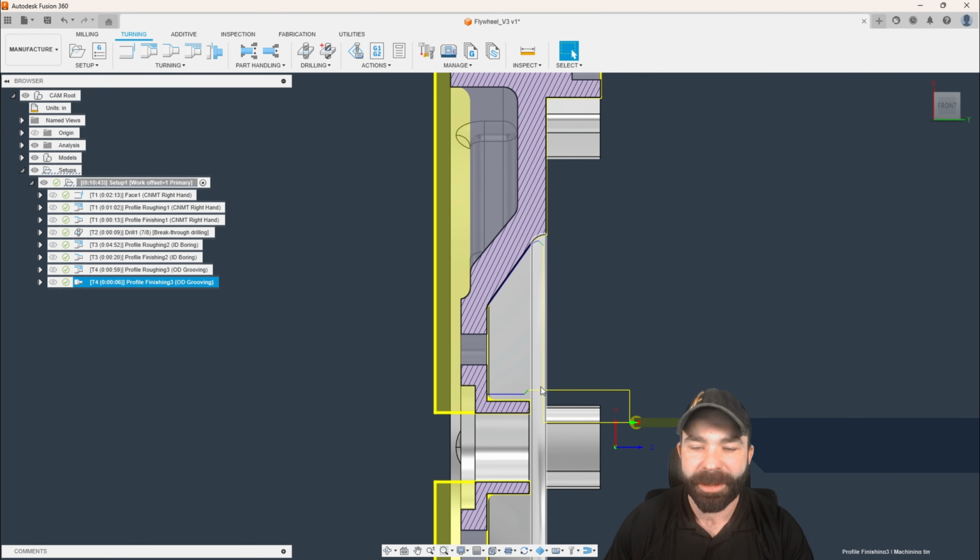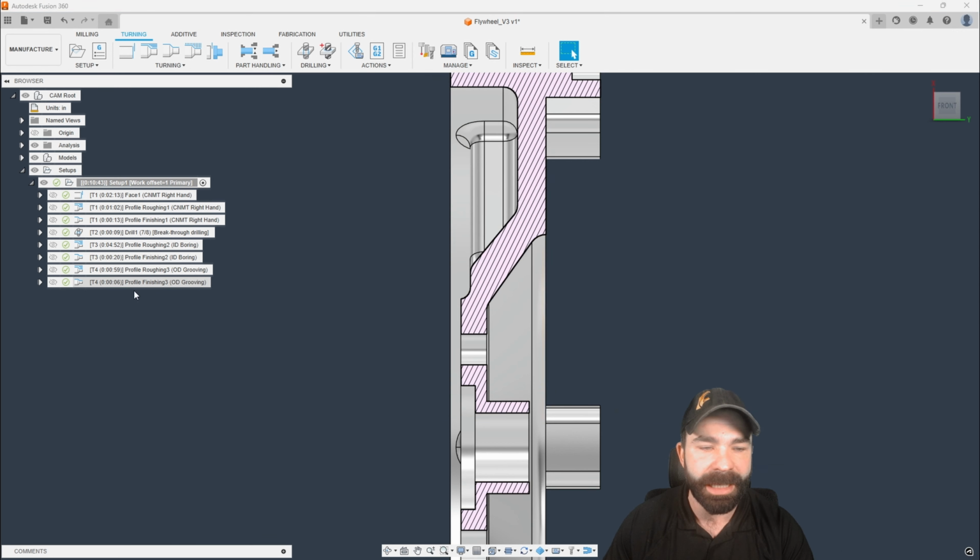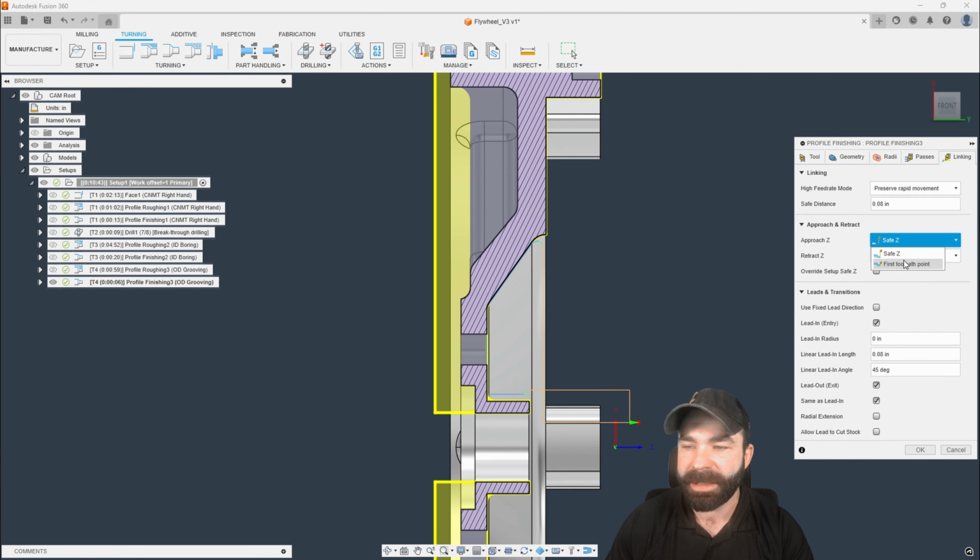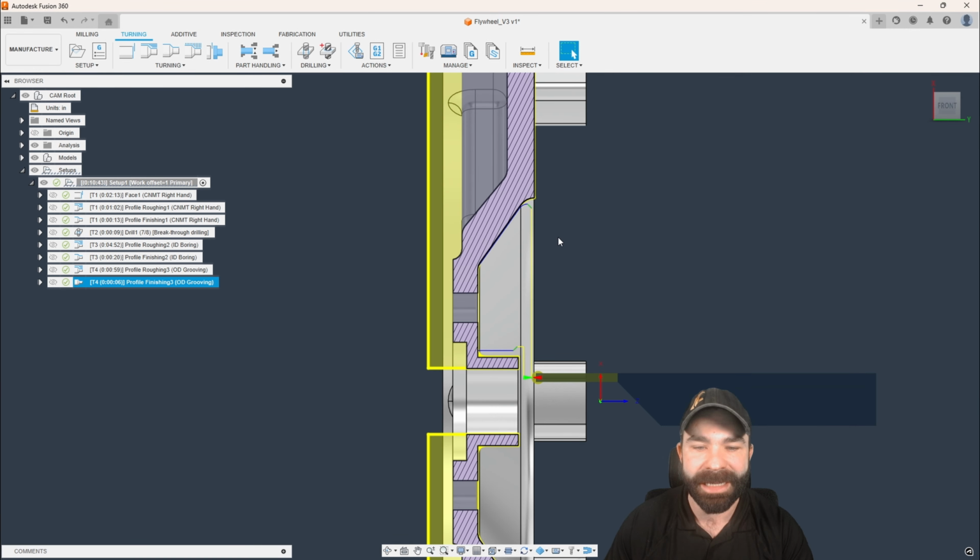If you guys want a little different example of first point, last point, you could go ahead and play around with this here, where you save first point, last point of toolpath. And again, because of the way our clearances are working, it's always coming back to that clearance height versus starting in our part at those locations. So you do have to adjust that as needed.